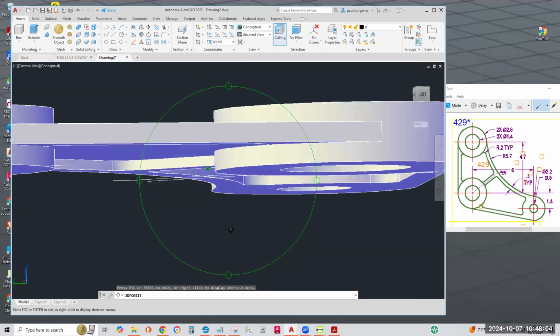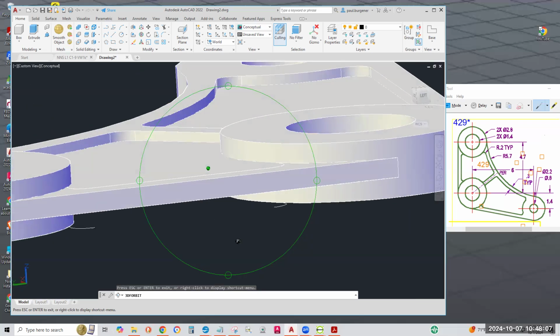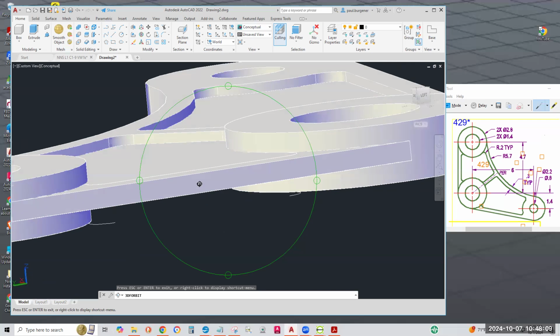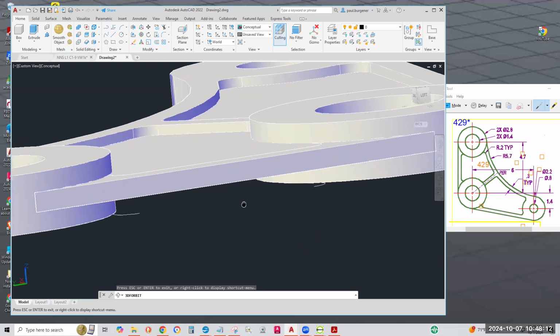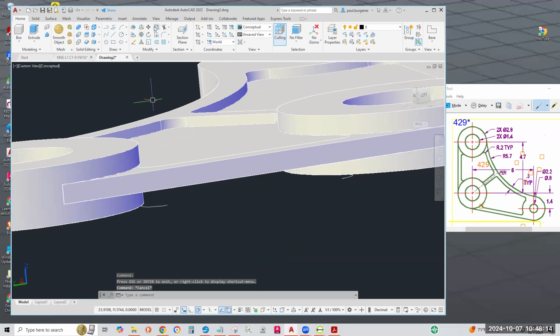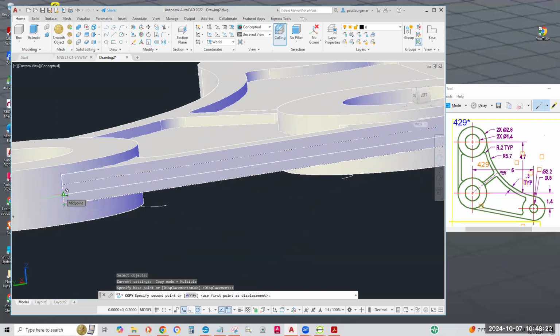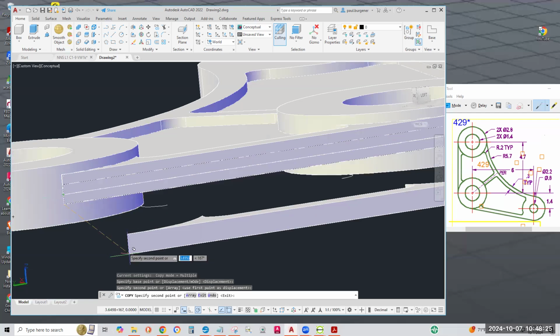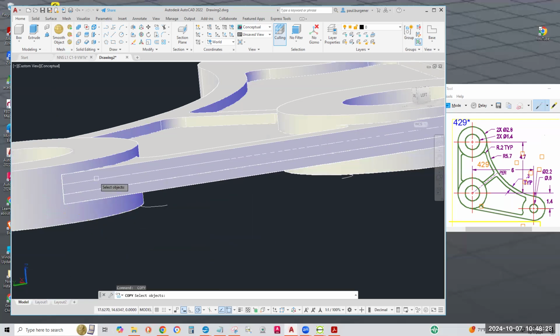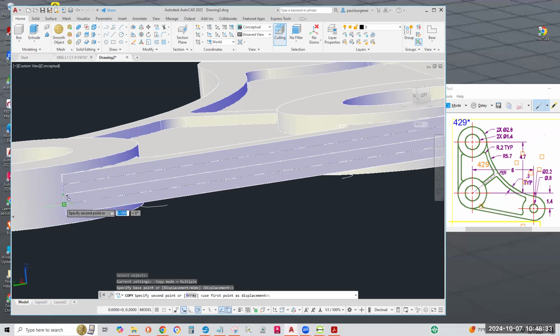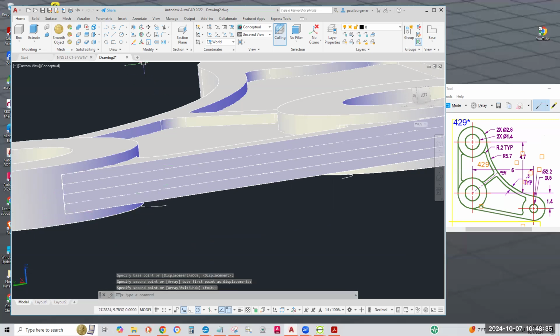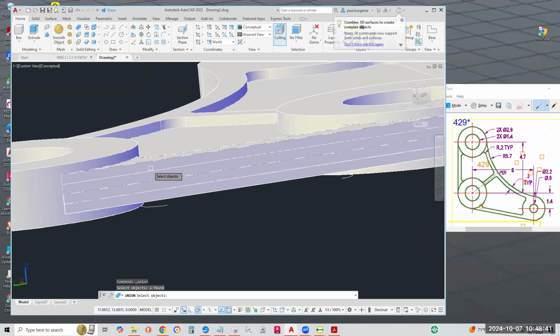We can move everything that's solid straight out. And I'm going to copy this guy 0.1 up and 0.1 down. Okay, let's copy, select this flange, enter. We'll go from here to this midpoint. That's exactly 0.1 because it's 0.2 thick. And enter, enter. We'll copy this bottom one, replicate it from endpoint to midpoint down. Good housekeeping. Let's union these three together.